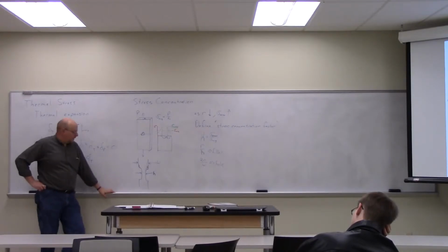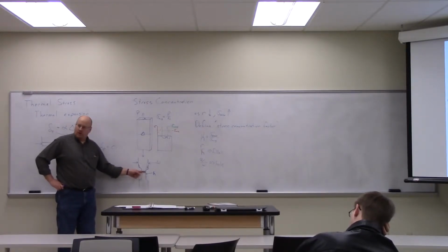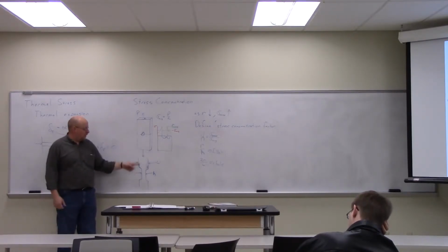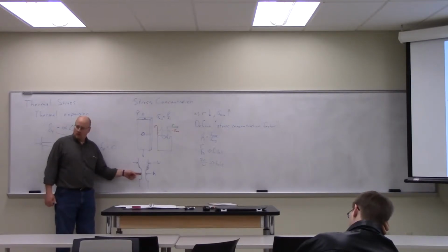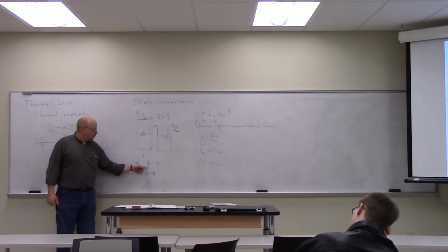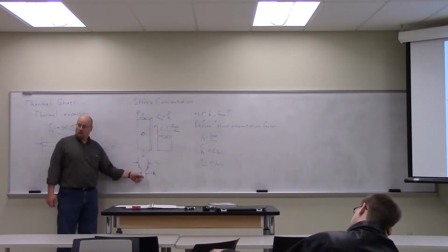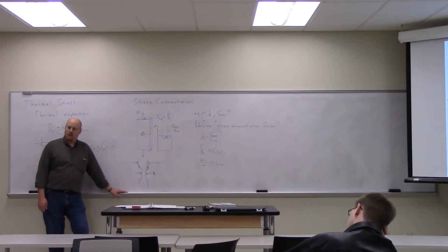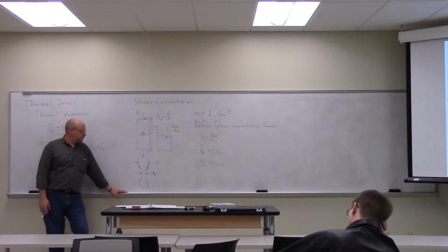Right, yeah. Because the actual strength of the bar is limited by this. The smallest dimension, right. So we're concentrating relative to this dimension. We're removing material in an area that isn't experiencing the greatest stress, in order to make sure that the region that is experiencing the greatest stress right here has a reduction in stress. So it's a little counterintuitive, but it makes sense.